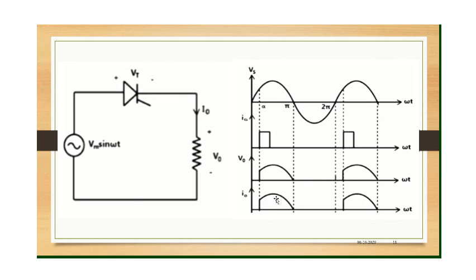Even the current, as you can see. Now, in the next half cycle, when the supply voltage crosses zero, it goes reverse, right? So the reverse voltage, when it is applied to the anode terminal, the SCR turns off. So when the SCR turns off, you don't get any output at the load. I hope you are able to understand.